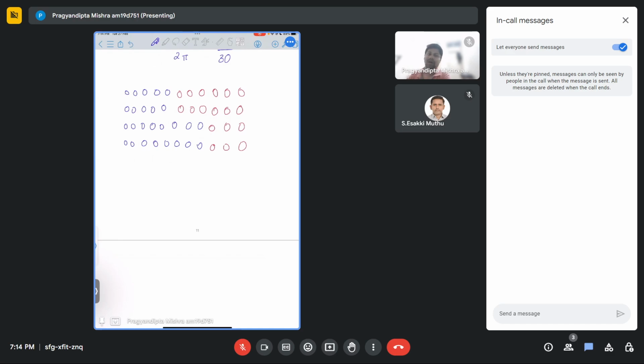Now, essentially, when you look at dislocations under a microscope, you will not be able to distinguish between what an edge dislocation or a screw dislocation would look like, because you'll have mixed characteristics within the dislocation itself. Essentially, we are defining edge and screw because, based on how the dislocation could be formed, we want to say this particular dislocation has an edge characteristic or a screw characteristic. Now in edge dislocation, what we'll have is,